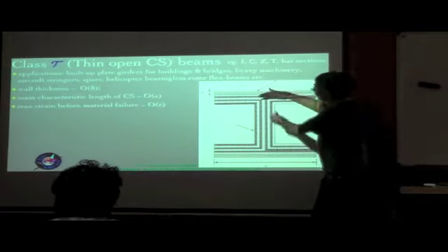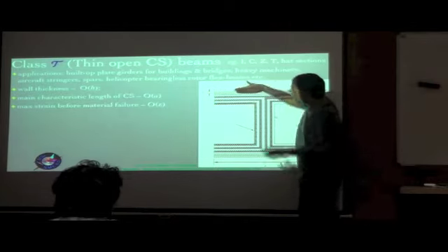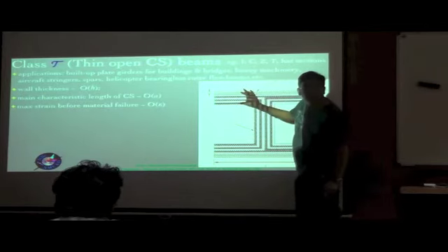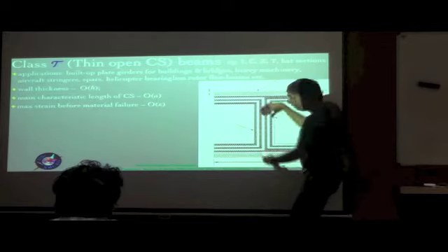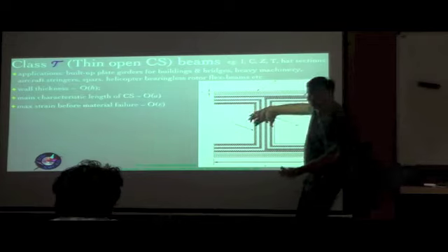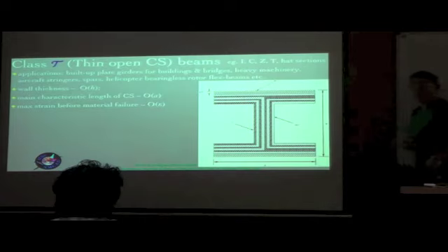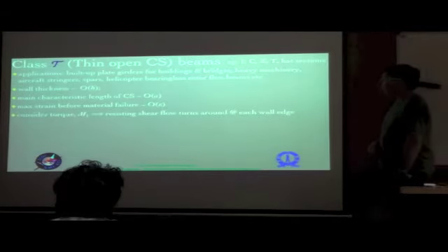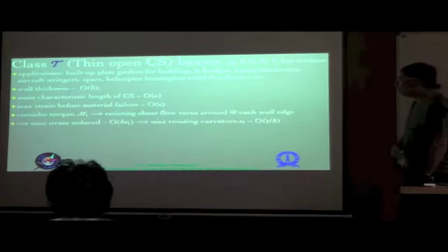Okay, and if you look at each component like here, the moment arm that shear flow has is basically because of a couple that is over there, and so the moment arm is of the order of magnitude of the thickness. Again, here the shear flow at the 2 edges basically going like this, and again the moment arm is of the order of magnitude of the thickness. So that's what creates the issue here in terms of lower torsional stiffnesses, larger kappa 1 or twist per unit length.